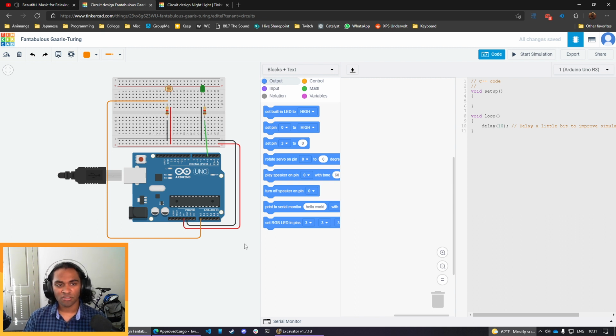Sweet. Okay, so what we're gonna do here is think about the logic. Think about what exactly we wanted to achieve here, right? So we're saying that we're gonna get a value. Remember, our photoresistor is connected to one of our analog inputs. We said that our analog inputs are going to give us a value anywhere from 0 to 1023, right? So we need to somehow make a determination of, okay, if the value from the photoresistor goes past